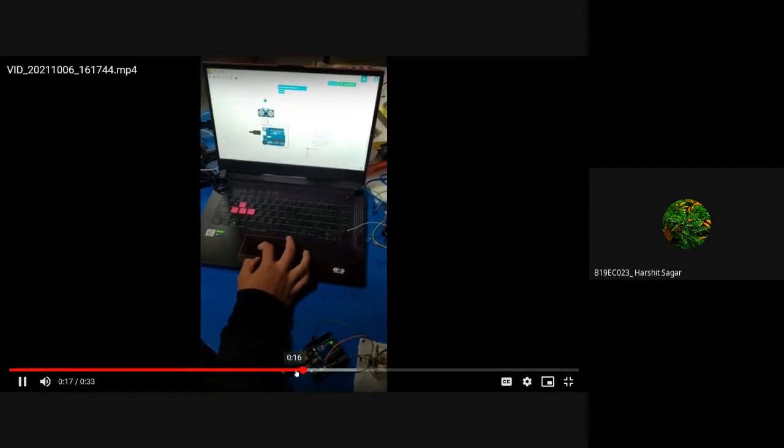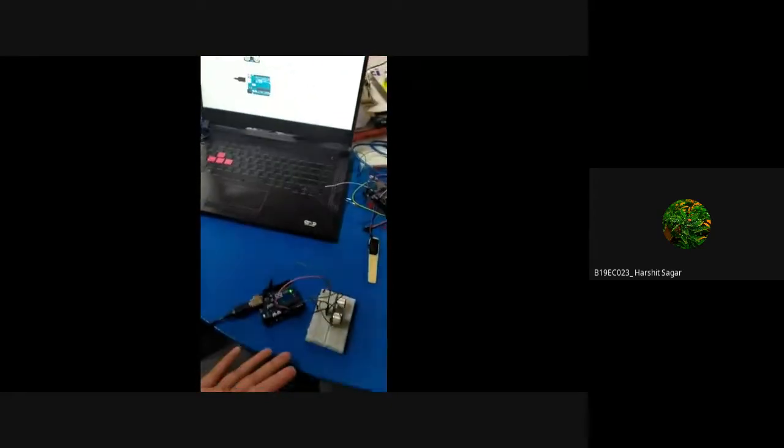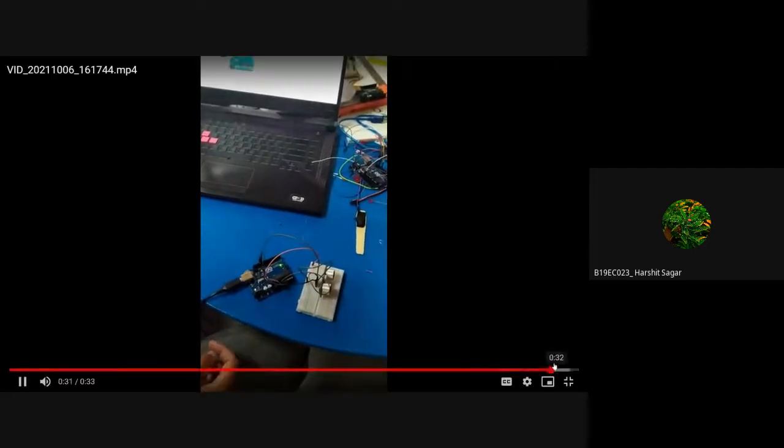In this video, we are covering the speed measurement instrument using the ultrasonic sensor. What we are basically doing is calculating the distance, and through it we are calculating the speed and acceleration of the object near the ultrasonic sensor and showing the output. This is the object that we have used, and as we can see in the serial monitor, there is a change in the speed, the acceleration and also the distance of the object. We also tried to implement a model of this code, but due to some technical errors, it is not working.